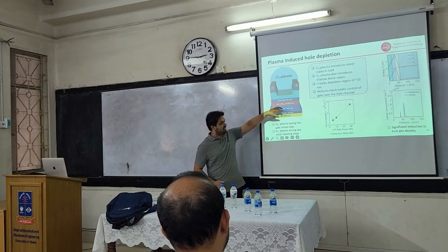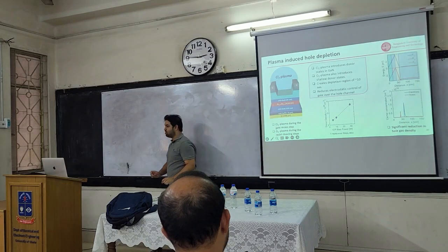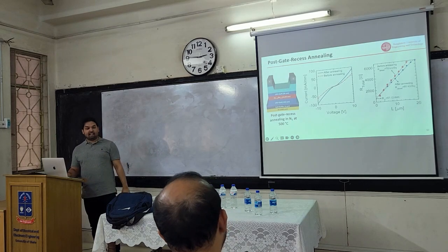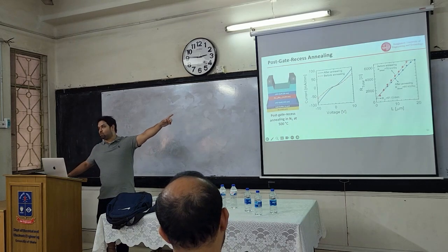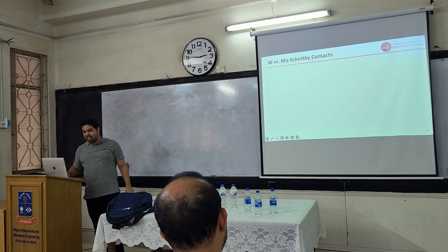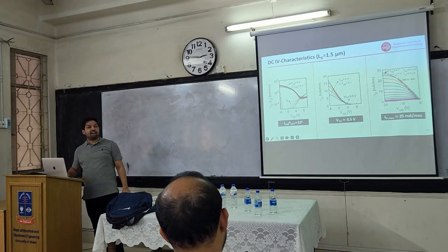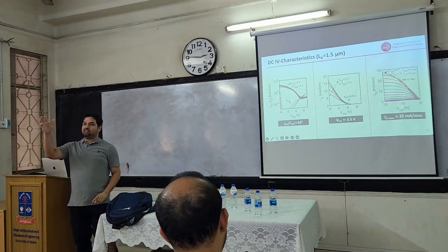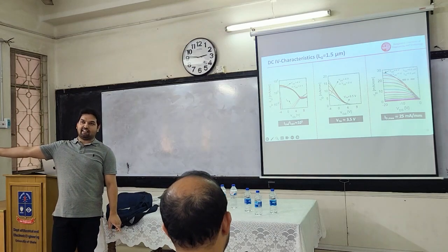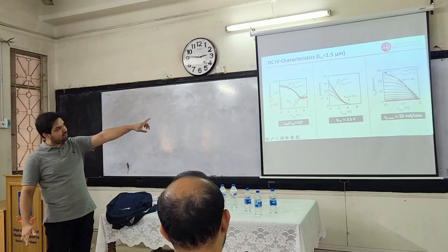So after the etching, after cleaning the sample, we do an annealing in nitrogen, and actually that solved the problem. And you can see that the sheet resistance goes down after the annealing. And with that, I made planar device again. So I started with planar device, made FinFETs, right? And then did the process development, and then started with the planar device again.